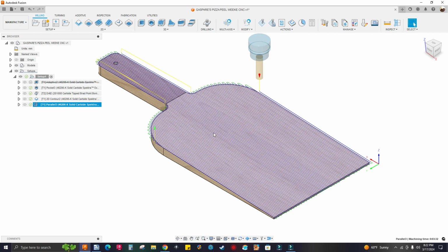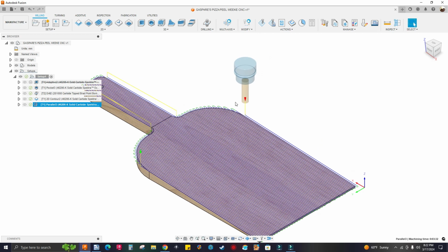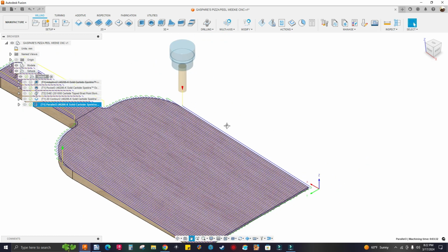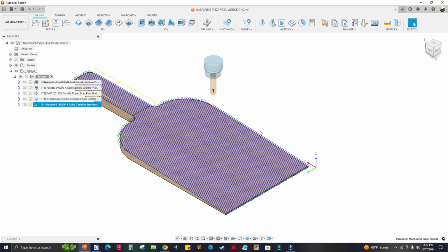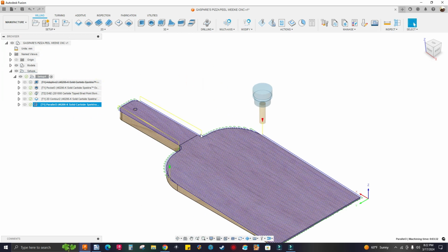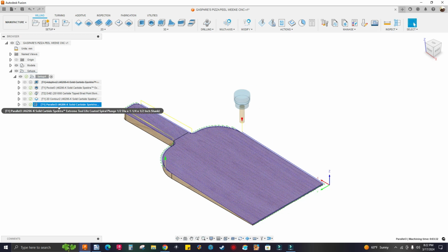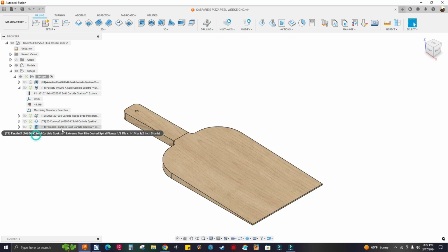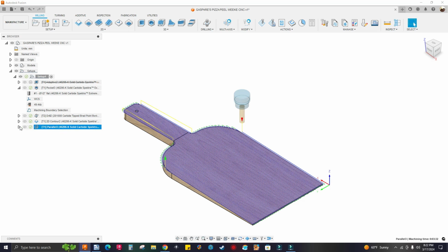Look at that. You have a nice, consistent toolpath. See that? So the tool's gonna stay down. It's gonna track here and then here. If I check the size of the file, so I'm gonna click on this arrow. See how small that is compared to the other. It's smaller, but this is gonna be easier and faster to load and run on your machine. Okay, I can make this even smaller if I want.